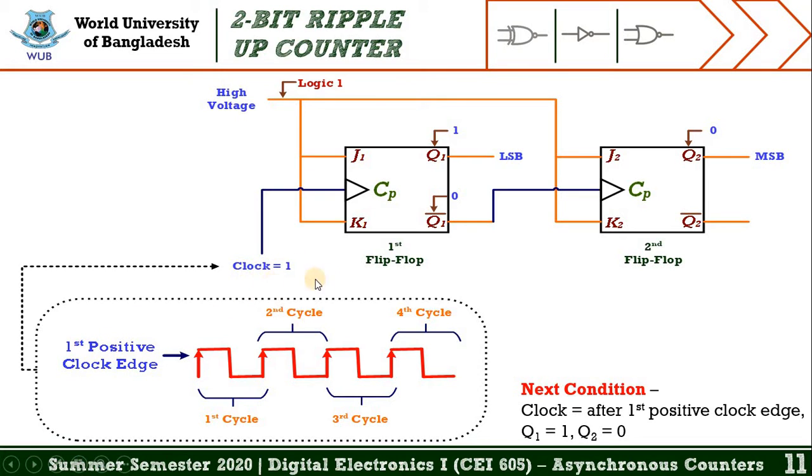That's why the first flip-flop is activated or triggered. In that case, we get the output value 1. If we complement this output, we get 0. Why do we need this complement? Because this complement acts as the input or clock signal for the second flip-flop. That's why we need the complement of this output.